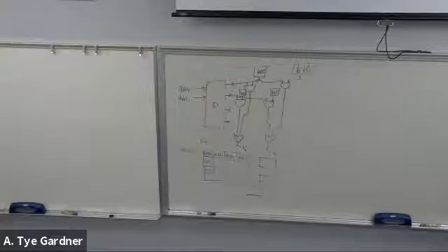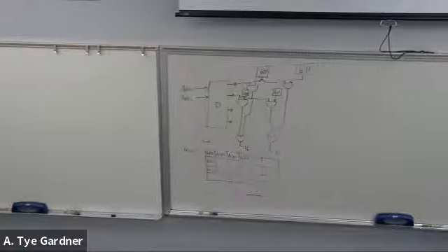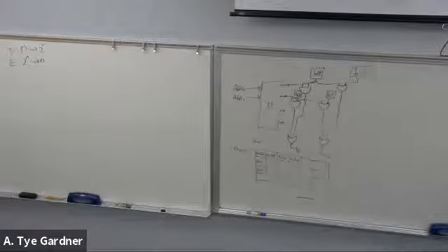We have time, we'll come back to a real world application of muxes that's kind of interesting. But for now, I'm going to move on to encoders. So encoders are the opposite of decoders, where before we had n to 2 to the n, now we're going to have 2 to the n to n encoding. Encoding, decoding. Okay. And I have to change this, sorry. So decoders go n to 2 to the n, sorry, encoders go 2 to the n to n.